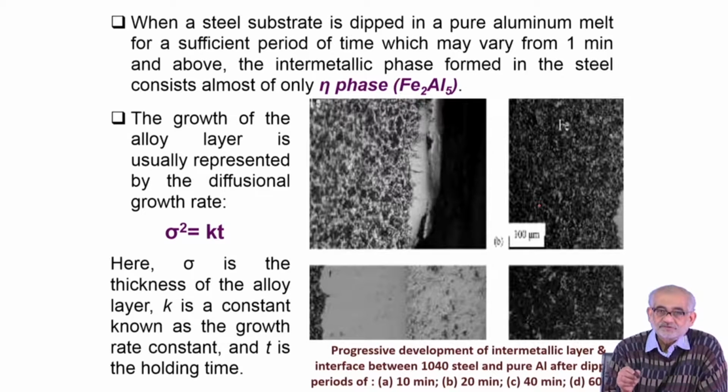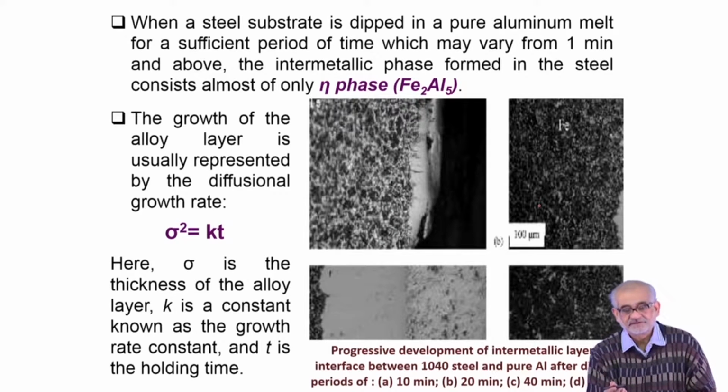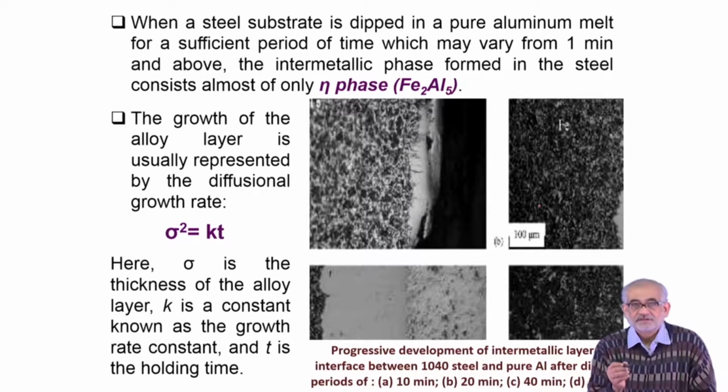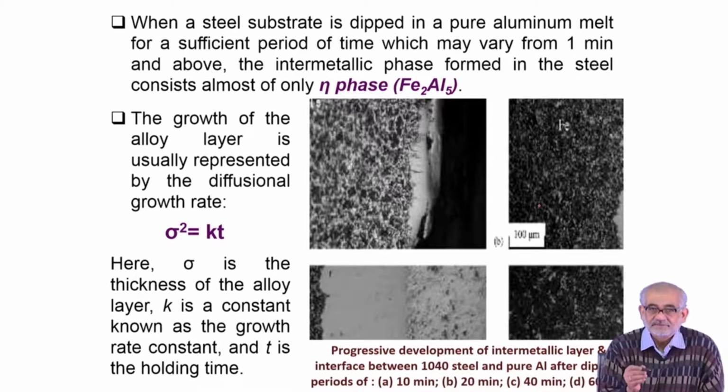Now, when you expose steel or nickel or titanium, elements which have high affinity for oxygen, to high temperature, you need elements to form a diffusion coating onto the surface which will sacrifice itself, form an oxide and prevent further ingress of anions, for example oxygen. Now this is done not necessarily through a solid solution layer.